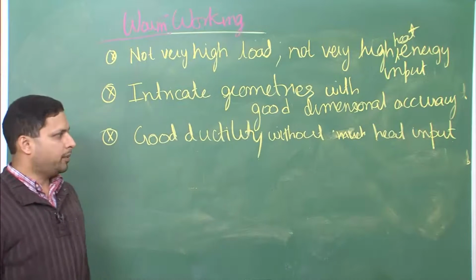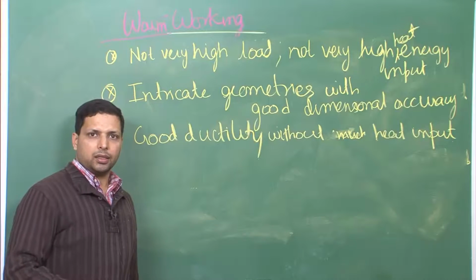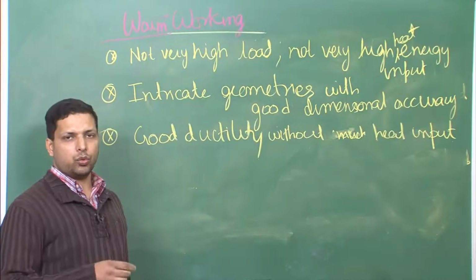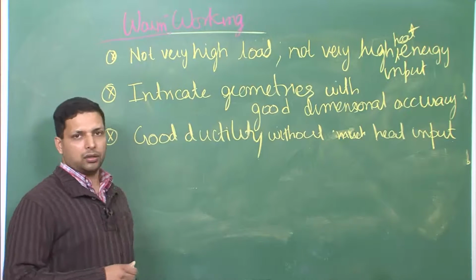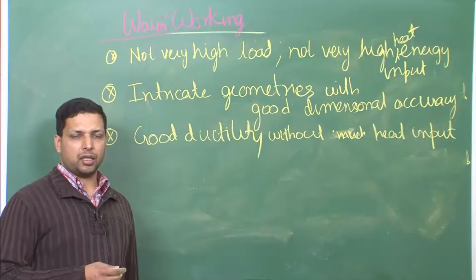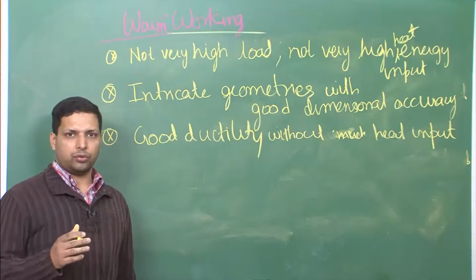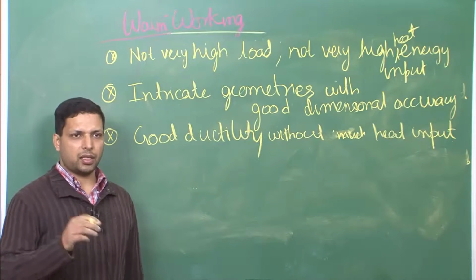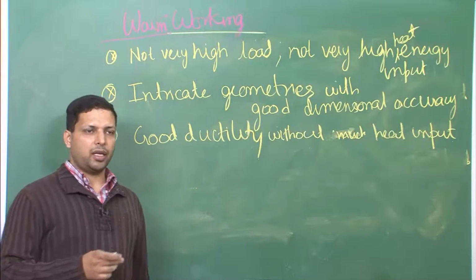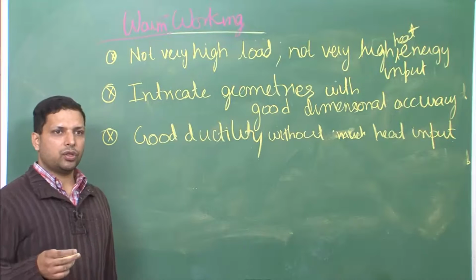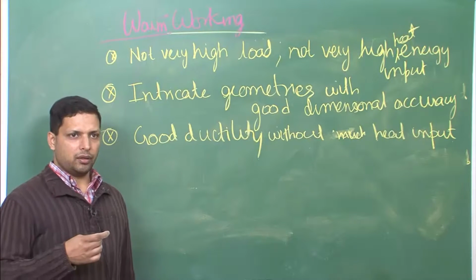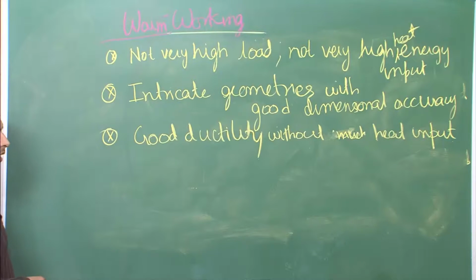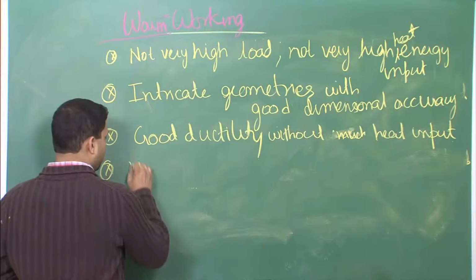In cold working there was a limitation because the grains keep accumulating the dislocations or the defects, and eventually it will break. But when you are doing the deformation at warm working, the material is able to relax, to put in quotes, to a certain extent. And why is that? Because the dislocations form cell walls, they are able to minimize the energy in the microstructure by forming cells and cell walls, and therefore the material is in a better position to accommodate more strain, and therefore you are able to get a little bit higher ductility than you would get in cold working. Very little scaling.